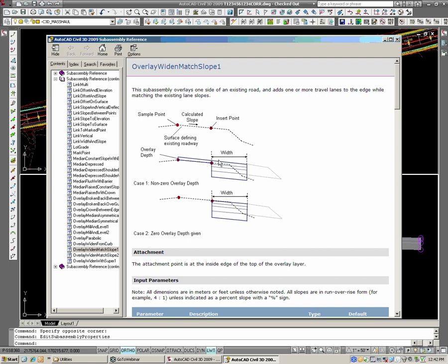So I'm going to set this on top of my roadway. If I don't need to worry about adjusting slopes of my road, like we do with this minimum 2% business, I could just set this right on existing grade. But then you're going to get the slope of the existing grade, so your survey better be pretty good and accurate, and the triangles in your roadway need to be looked at and made sure they're right. But you could just set this right on existing grade, no problem.